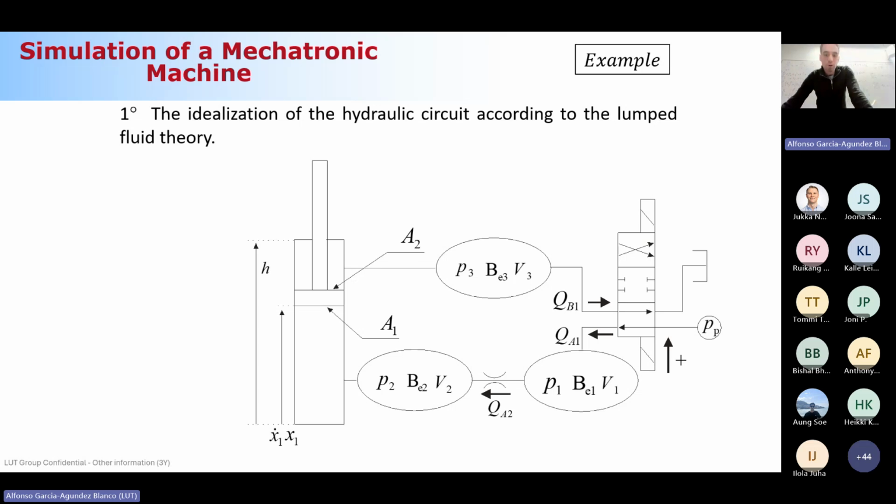But here, for example, in this control volume, you agree with me that I have oil, I have a hose, but apart from that, I have what? A chamber, and the chamber will have a different flexibility. So in the computation of the bulk moduli, you need to take into account all the different components and the associated flexibility. I will show you now in the exercise.